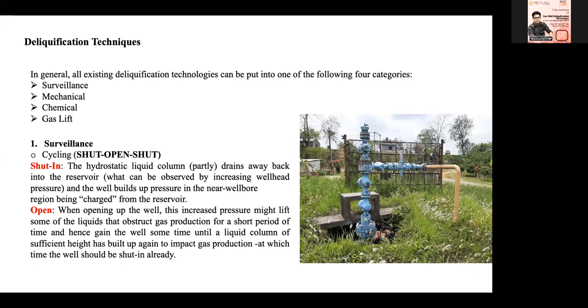In the wellhead, we have a stack of valves. Like I said before, the wellhead is a stack of valves. You have your bull plug, you have your bull plug flange, you have your swab valve or your crown valve. Actually, this picture shows the back side of the wellhead. You are going to see a wheel on the front side for these valves to open or close. You have your swab valve or the crown valve, you have your flow arm valve, and you have the upper master valve and the lower master valve.